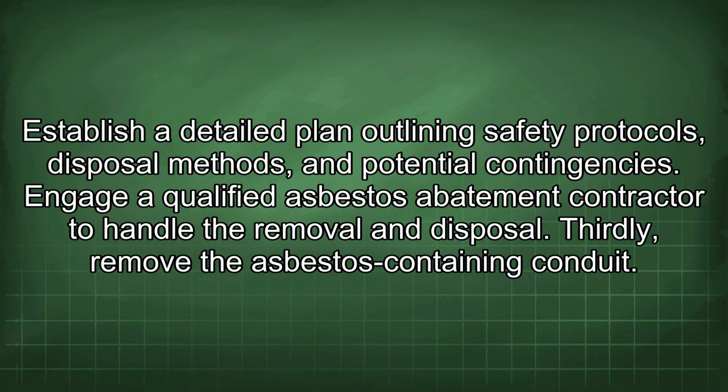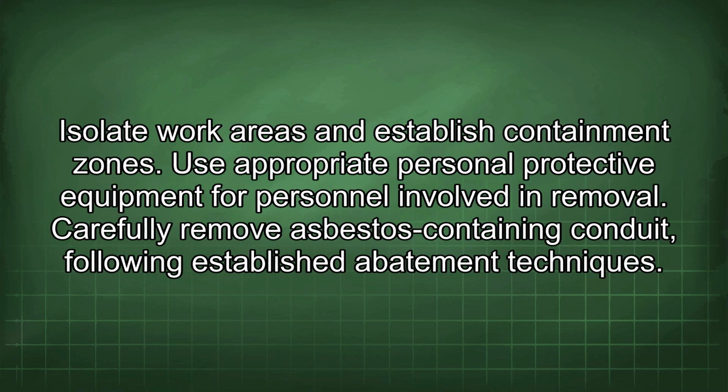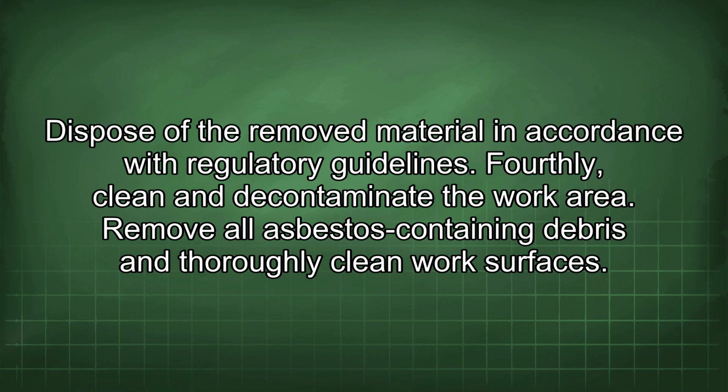Thirdly, remove the asbestos-containing conduit. Isolate work areas and establish containment zones. Use appropriate personal protective equipment for personnel involved in removal. Carefully remove asbestos-containing conduit following established abatement techniques. Dispose of the removed material in accordance with regulatory guidelines.